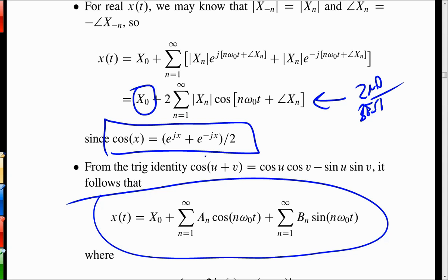And usually in a microwave or RF instrument, they don't want any DC getting in because it might destroy something. You might accidentally have a line that has a bias voltage on it, and if it enters the instrument, it might blow something up.